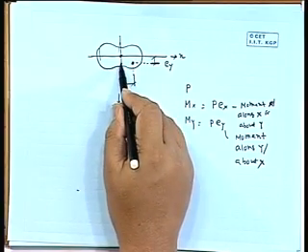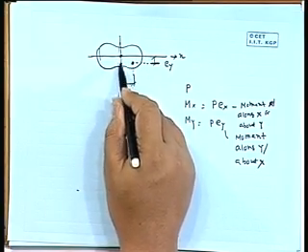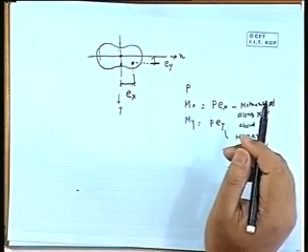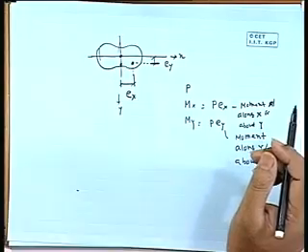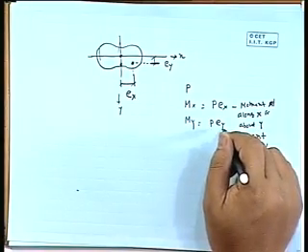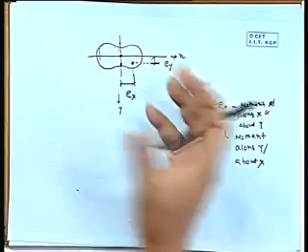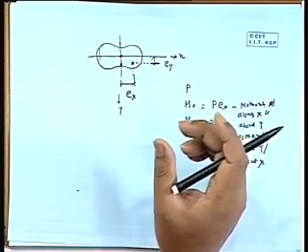So, once you bring it here, the next step is that there will be a moment about x or a moment along y. So, this part is P into Ey. So, there are two moments: a moment along this, a moment along that, plus there is a force. It is just like this: the force was here, we have shifted it there, so there is a moment along this and a moment along that. So, it is a biaxial moment, right.